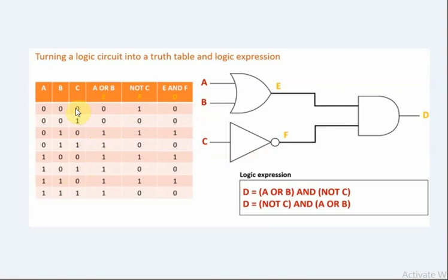Here C gets 0 but A and B are also 0, you can't. Here C gets 0 but A or B is 1, B is 1, therefore you see the output is 1, it's possible, right? Here you can't, again here C is 0, A or B is 1. So here A is 1, therefore you get the output 1. Similarly here C is 0, A or B needs to be 1, both 1 means no problem, no? At least one of them is 1, so both 1 means definitely you are getting 1. And you can place all others 0.